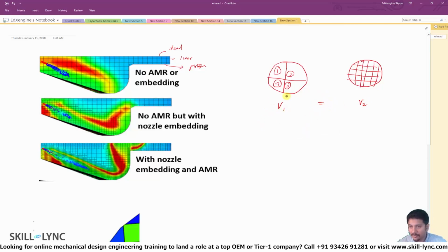If you take a look at other software, depending upon the number of mesh points, your entire surface might get approximated. For example, if you just have 4 points, you will end up with a shape like this, which is not even a cylinder. If you increase the number of points, you will slowly start recovering the cylinder shape. By the time you get to a very realistic representation, you might have to use a large number of cells.